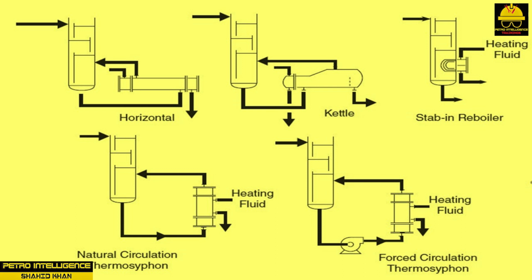As the bottoms product comes into contact with the tubes, a portion of the liquid is flashed off and captured in the dome-shaped vapor cavity at the top of the reboiler shell. This vapor is sent back to the tower for further separation. A weir contains the unflashed portion of the liquid on a reboiler. Excess flow goes over the weir and is recirculated through the system.